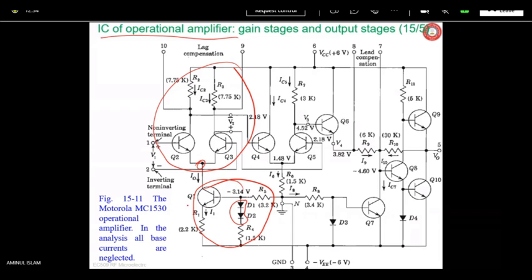So actually we get this amount of current, IC7. See, there is no current flowing through this because it is reverse biased. It is negative voltage, this side is positive. Or you can say 0, whatever it is, but the drop will be 0.7 volt only across this. So all current flows through this as a base current, because there is no other way for the current to go.